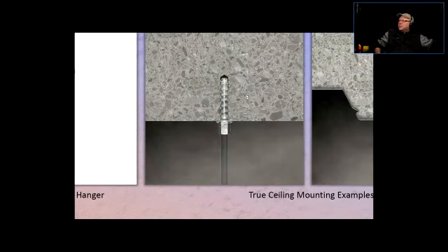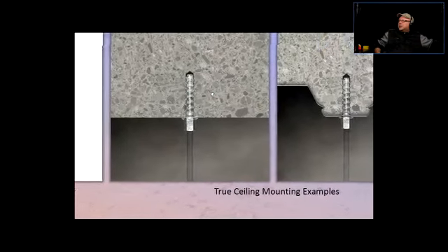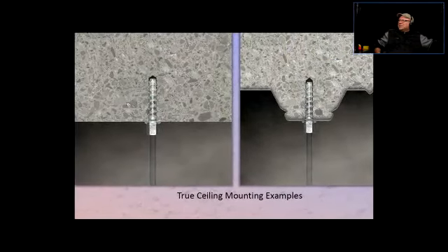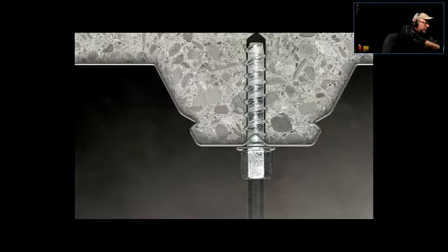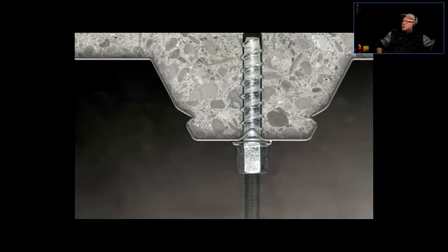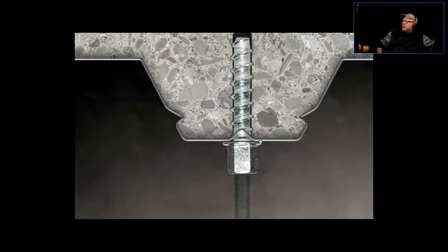Now remember I was talking about the perforated steel ceiling. So there's the pure concrete slab ceiling, and this is a ceiling that is covered with the perforated steel. I'm not sure if you can see it or not, but when you download it, you'll be able to see that steel. Now, the procedure of drilling that anchor into here is going to be a little bit more complicated, because first you have to puncture through that steel, all right?